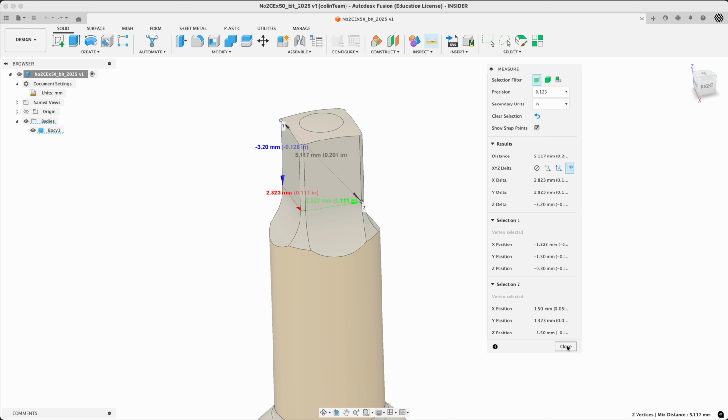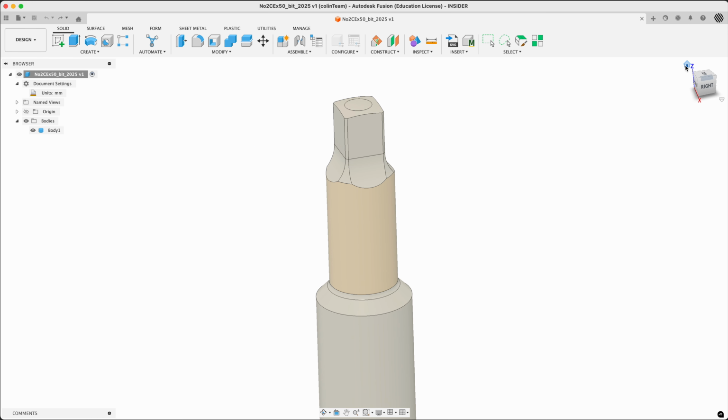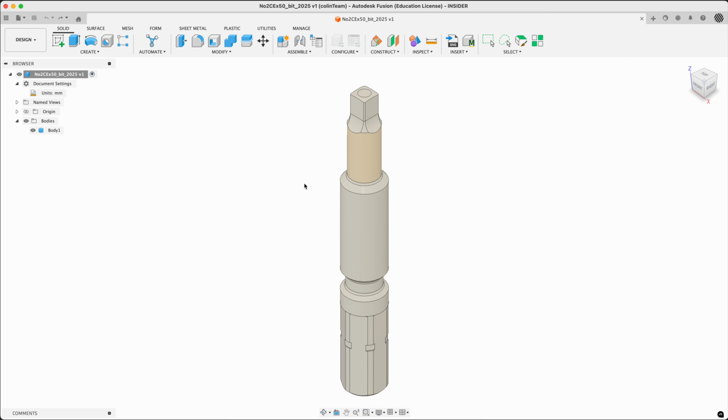However, it's fine, but it doesn't get past the problem of just collecting a bunch of data, probably on a separate little notepad. One solution to this is actually to sketch right on the step file. So we know that there's usually a sketch within these things. We're going to split the part. So search for split body, pick the body, and pick a face to split it with.